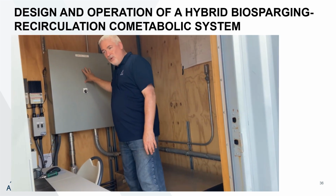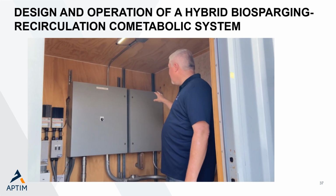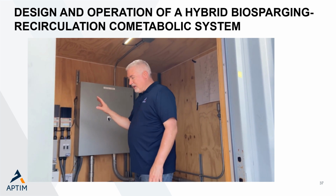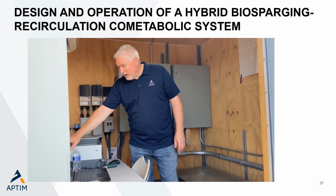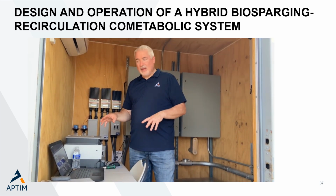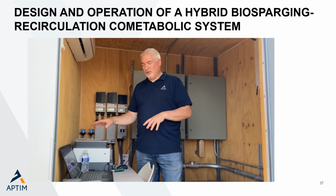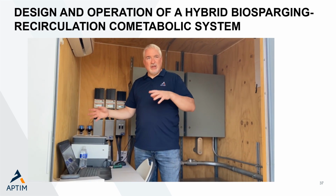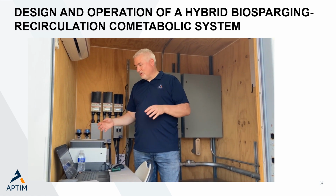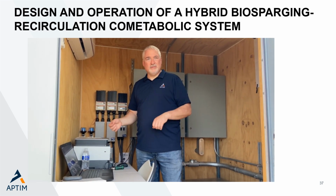This panel controls basically all, and the panel to your right controls the pump and all the 48 volt system components. That's all connected to a laptop computer. This has a SCADA system on it, which allows us to log and record all the data, and to see this data remotely. We are able to dial into this computer, see how the system is operating, make changes, and shut down the system if we need to. Several safety features are built into the system so that it will shut down automatically should certain high or low level conditions occur.